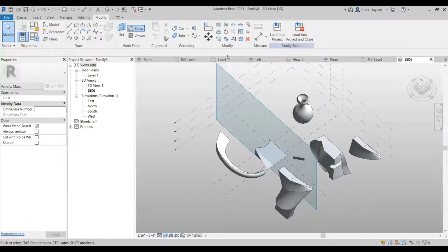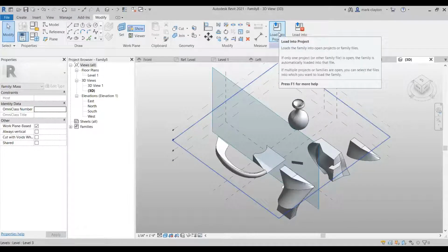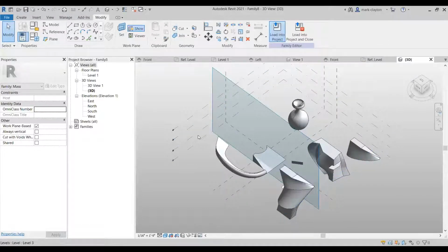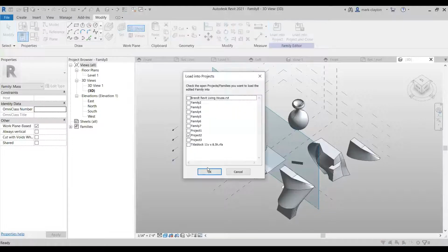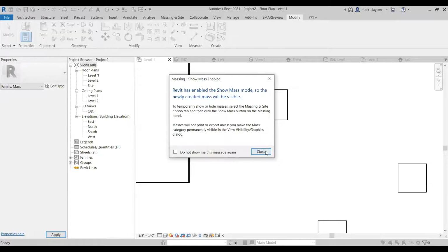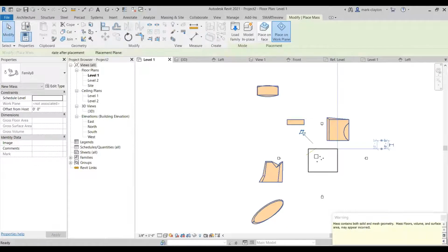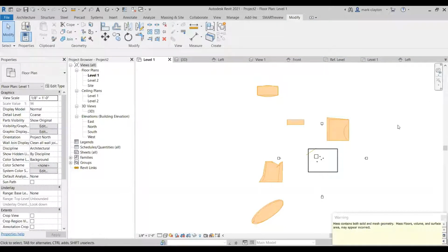All right, now you may be wondering, I mean, this looks like fun to create all these weird and strange shapes, but how do they become a building? And I can load this into my project file because the project file is where we turn things into buildings. And these are kind of the regulating surfaces of the building.